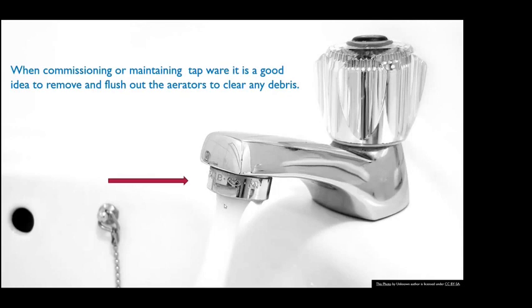But it shouldn't really be too much unless you get a big bit of thread tape or something stuck in there somewhere. But it could even be dirt. If you did a water main, you might have jammed the pipe into the dirt and not realized during the fitting, and a whole load of dirt comes through. So potentially those copper shavings could damage a new ceramic cartridge.